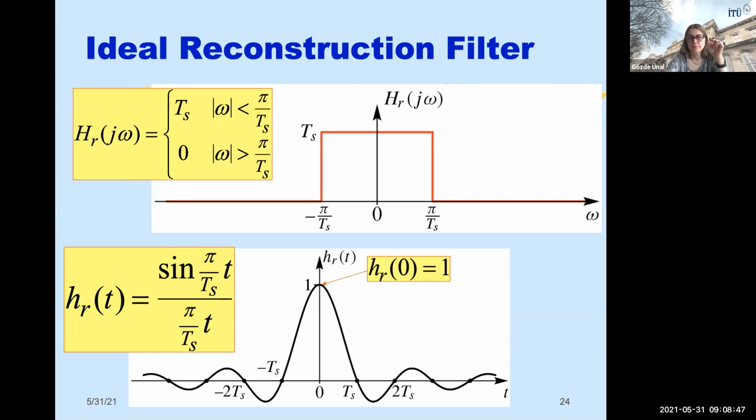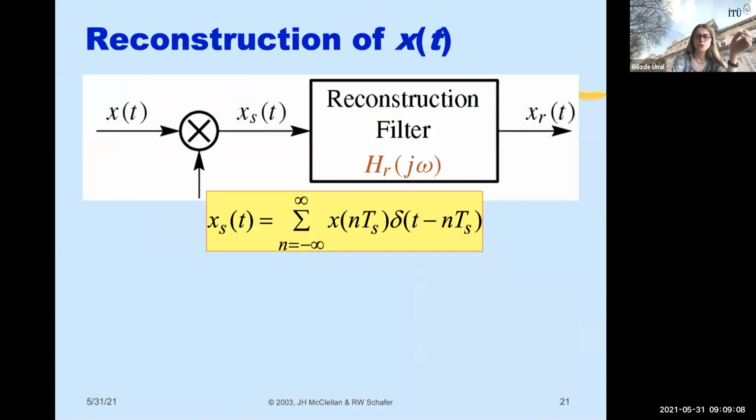Okay, here is the point. Look at the main lobe of this sinc, meaning the maximum value at the center. It's centered and symmetric, right? Nicely. So we will now see in time domain what is happening in this ideal reconstruction, which was very easy to see in the frequency domain.